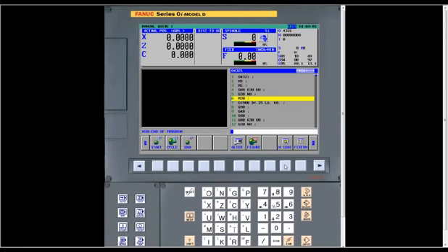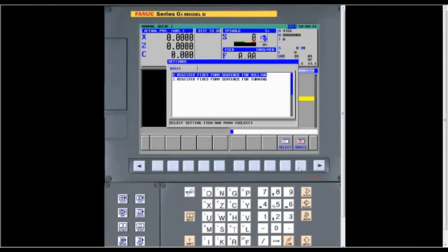Now, I showed you my fixed forms, and after this is over, if you need to, contact me direct. I can help you develop these fixed forms. But then to actually make them yourself, if you go right shift, until you see a soft key called settings. You go into that, it takes you into the basics where you can either set them up for milling or turning.